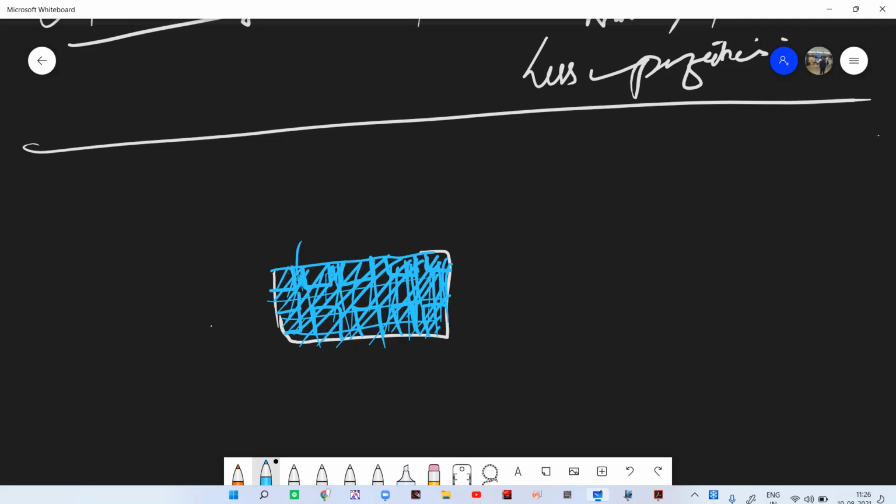Before that you need to mask the pattern. The masking is important, otherwise your pattern will be damaged. Once you mask it, take an electron beam, or a focused ion beam, and apply it with high momentum and high energy, and then remove this pattern. But there are different sources for removing.